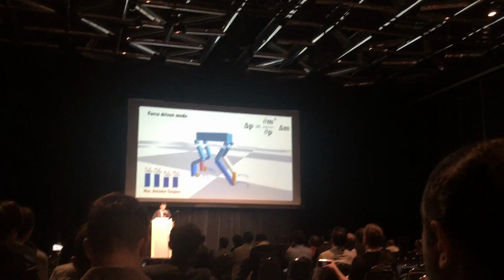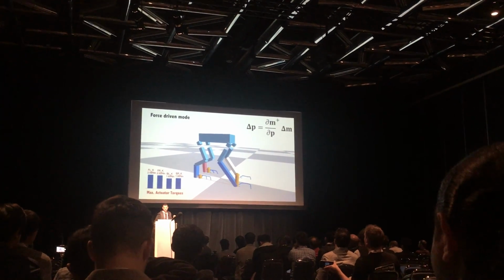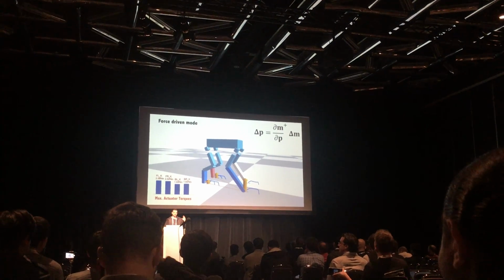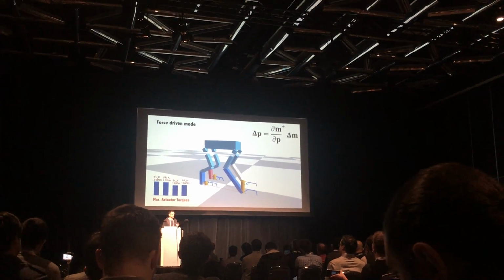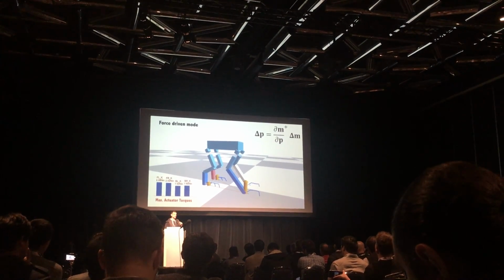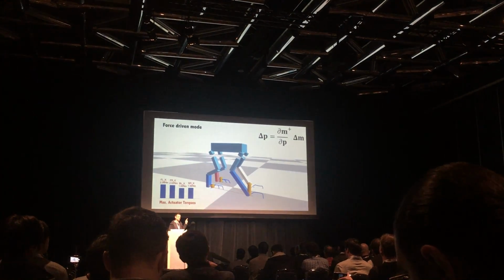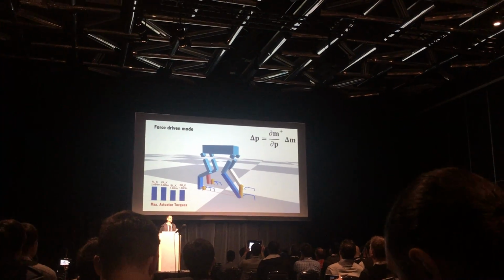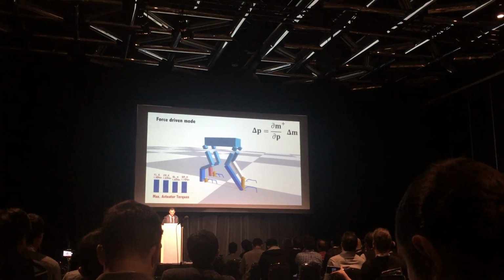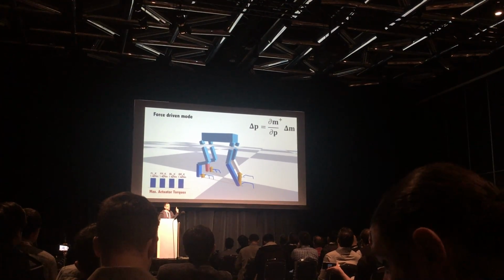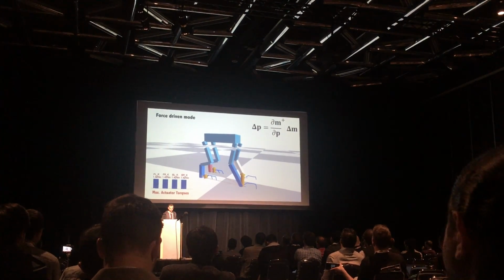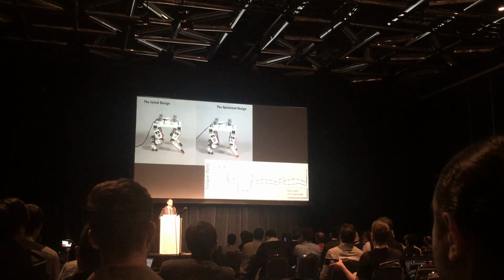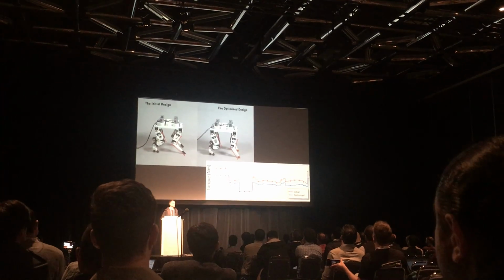Now, this is a very simple way of using the Jacobian that I was describing earlier. If we want to change some aspect of the motion, for example we want the actuation forces to decrease, to get lower, then we can come up with a corresponding change to the design parameters through the pseudo-inverse of the Jacobian that will make it so. This tells us how to update the design, and we can recompute an optimal motion rate, and so on and so forth. With this, we can see how this design changes automatically to decrease the actuation forces. If we look at the forces required to carry this payload before and after the design optimization, we see roughly 30% improvement.